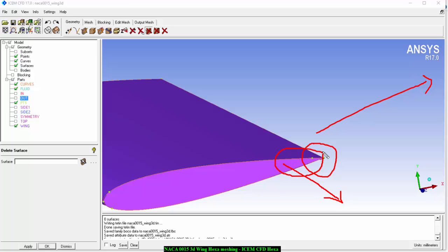That's why the blocking approach is going to be different as compared to the blocking approach for the aerofoil or the 3D wing with the square or the round trailing edge. Most importantly, in this 3D case, we also have a region or the block which is above this blade tip or aerofoil tip or wing tip that also has to be meshed.